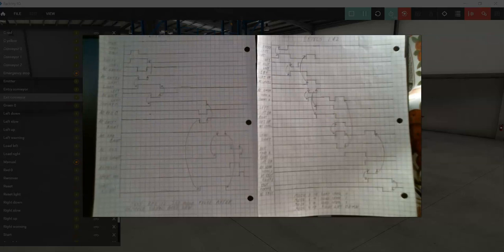Now, the leading edge of at exit left also turns on our conveyor. And the way I draw these timing diagrams is I put arrows on the signal. The down arrow is the leading edge of the pallet, and that's when the signal, for the retroreflector, goes from high to low, and then the trailing edge is when it goes back from low to high. So the trailing edge is later in time.